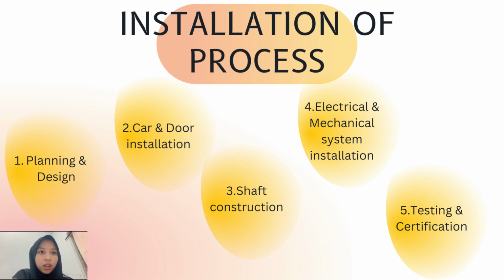The fourth process is car and door installation. The elevator car, including the walls, flooring, and ceiling, is installed within the shaft. The car is secured to guide rails and properly aligned for smooth vertical movement. Door operators are fitted, ensuring safe and synchronized opening and closing. The installation of safety sensors and emergency communication devices is also completed during this phase.